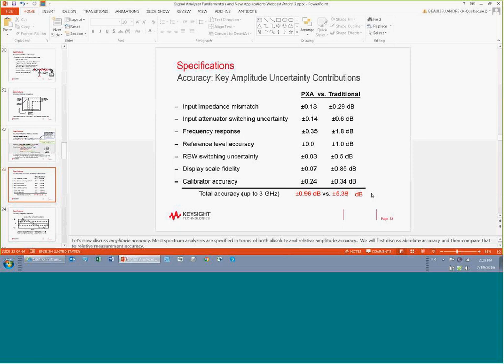And if I want to know the absolute power coming out of my transmitter, including everything, then I use a power sensor. But you could couple a power sensor with your spectrum analyzer and actually take a known source or a CW source and bring it to the frequency of interest. As an example, you bring it to 10 gigahertz, you go with a power sensor, and then you can fill a correction table on the spectrum analyzer. In doing that, you're eliminating the frequency response uncertainty, because you're not relying on the 50 megahertz signal calibration to calibrate the equipment, but you're actually using your own source, which you are measuring with the sensor. Yes.